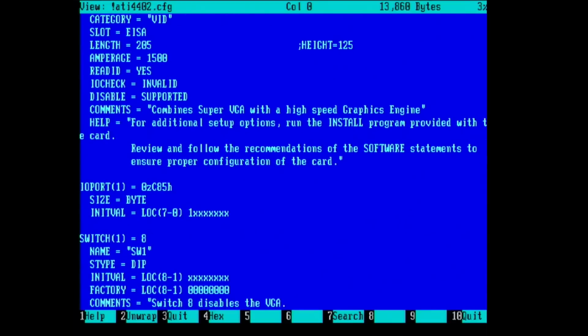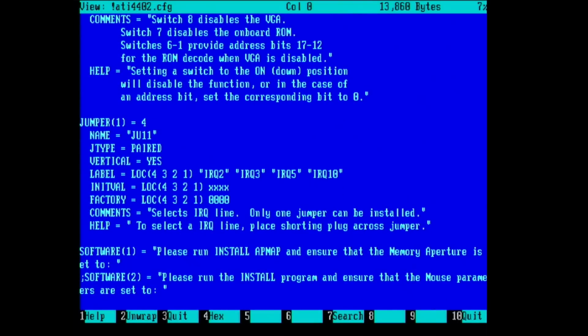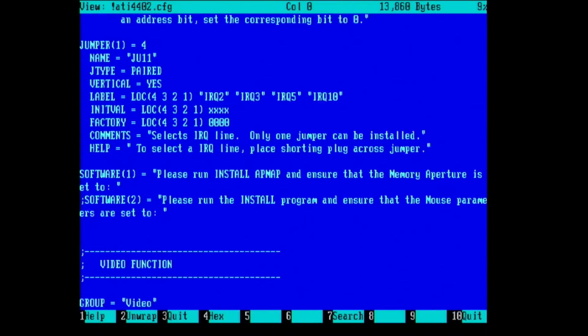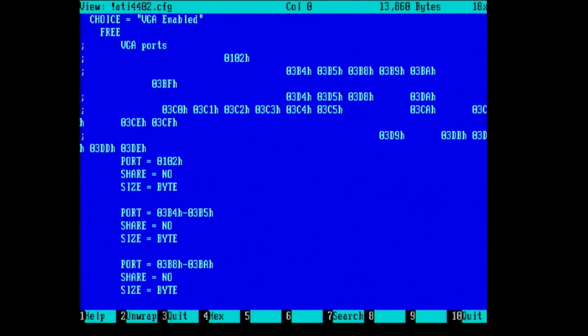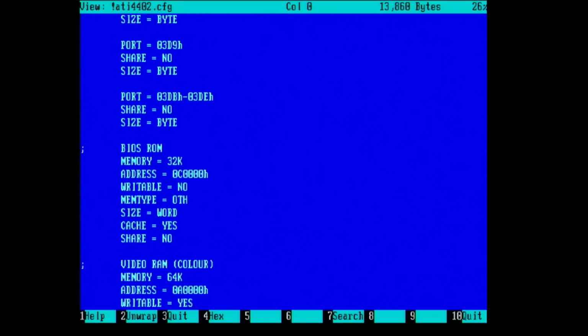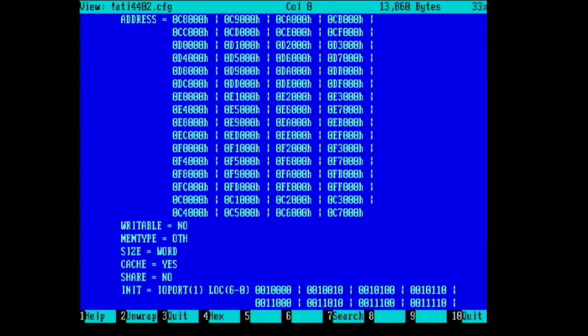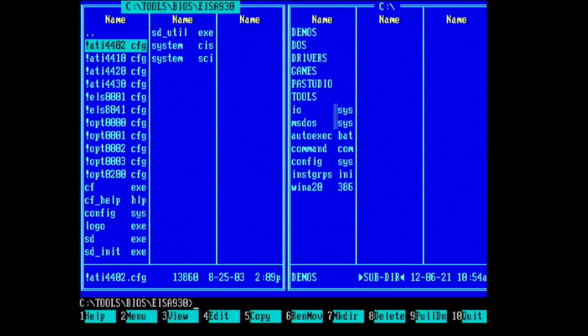Here we can see the documentation of the dip switches. So the configuration utility basically scans the directory for the configuration files for the hardware IDs found in the system. Those files represent the actual description of the hardware needed for the UI, configuration and also binary representation of the settings saved in the static RAM. The configuration files were similar like drivers and were provided by the manufacturers of the hardware with the actual drivers on the floppy disk.